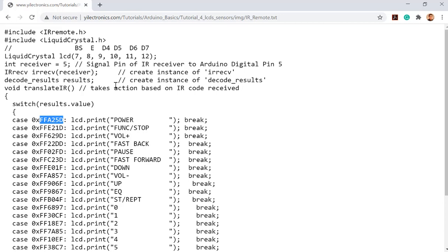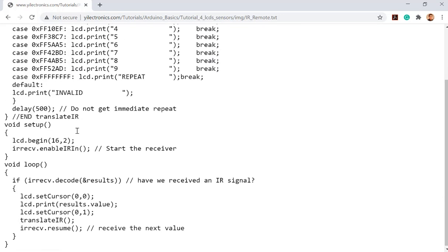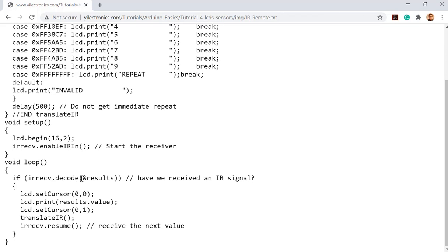So here's example code, okay? And you need to figure out the code behind every single push button. So turn on the serial monitor, make the hardware connection, load this sketch, and delete all the redundant things. Whenever you push a button, you don't need to know what is in this variable, because everything will be stored in here.